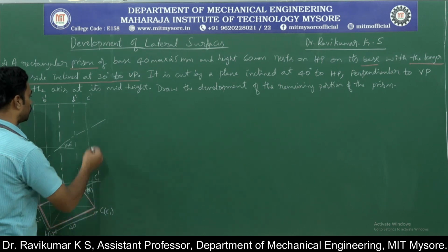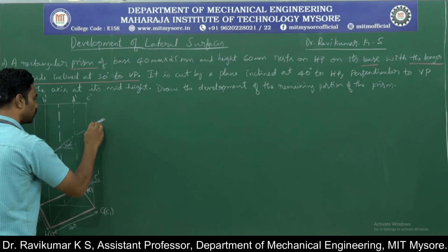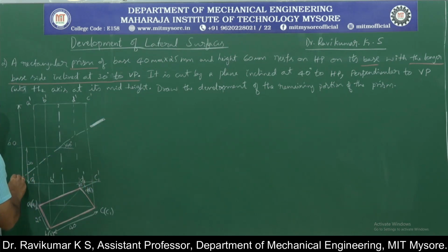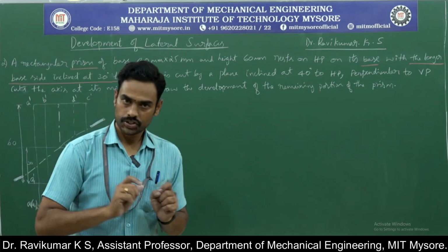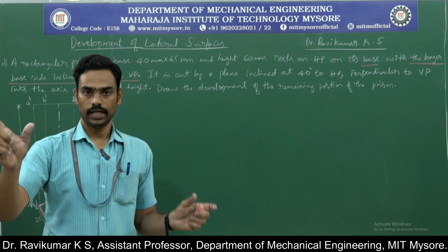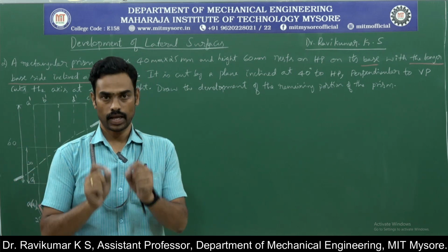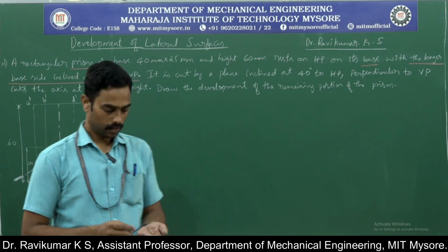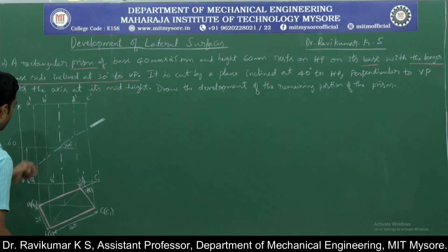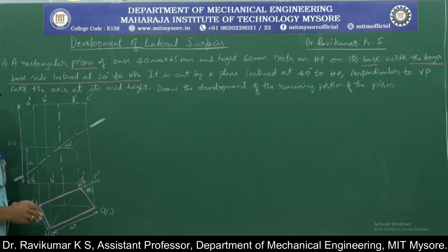So, the section line should be thick at the ends. This is thick at the end, this is thick at the end. Okay, section plane, you need to write it as a chain line, thick at the ends. That is the fashion of writing the section plane. Each and every line in a drawing has its own meaning. You need to use a chain line which is thick at the ends to represent a section plane.